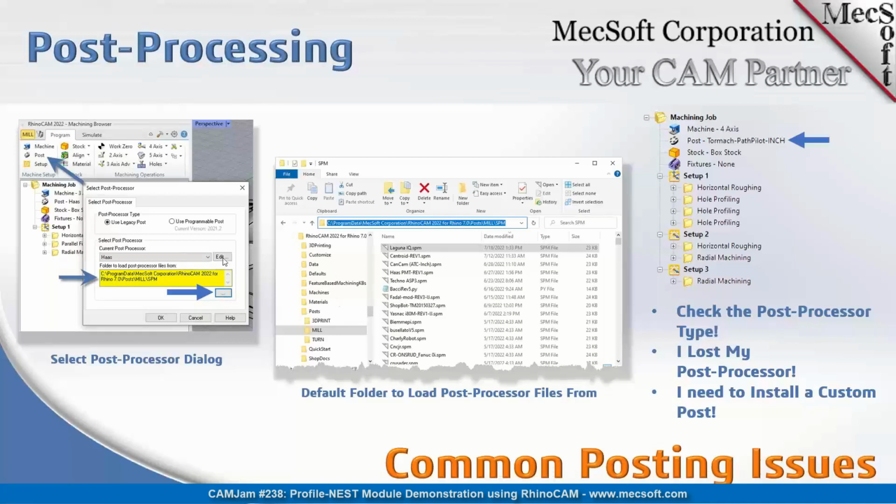So basically you want to start from scratch, go to the program tab, select post, make sure you're using the correct post type, then check out this folder where this dialog is currently pointing. What you can do is highlight and copy this folder path and paste it into a file browser, press enter, and it'll take you to that folder location.